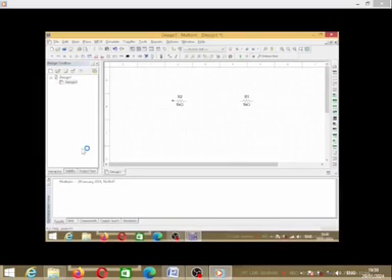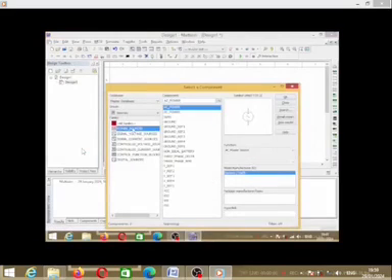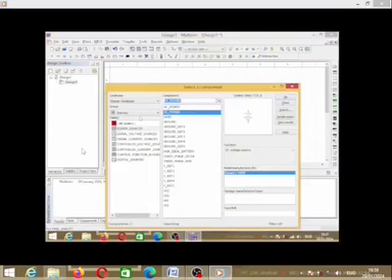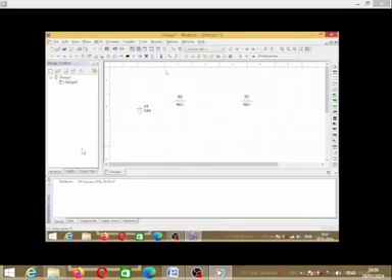We're going to copy and paste that on the panel. So now we have 2 resistors, and then the next thing we need is a power source. So we're going to have a DC power source from the components menu. Before we extend the links between resistors 1 and 2, we can change the values of the resistors from 1 kilo ohm.